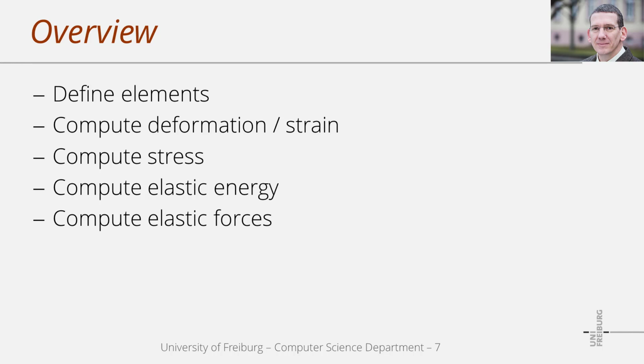Finally, we compute the elastic forces at the particles from the elastic energy of the element. Here we basically compute forces that accelerate the particles into directions where the elastic energy is minimized. An undeformed element has zero elastic energy, so when we try to minimize the elastic energy, then we actually try to restore the original undeformed shape of an element.